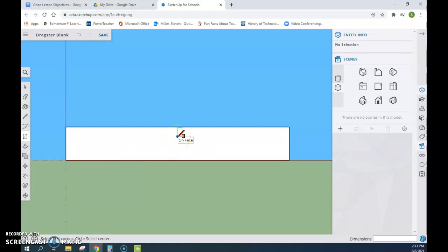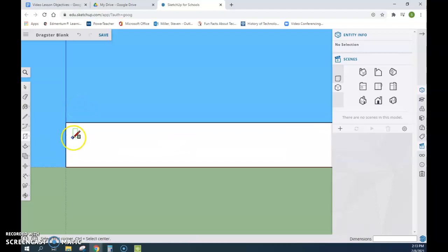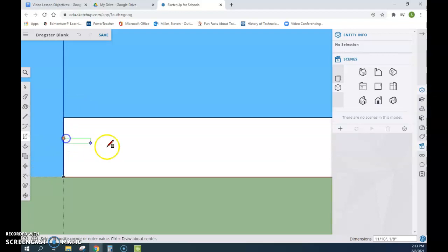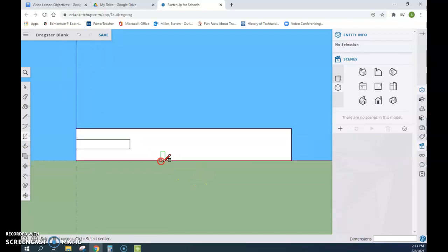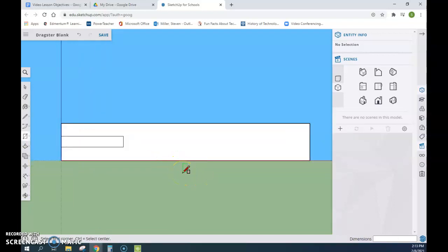All right. So now I'm going to go ahead and hit the space bar, and R for rectangle again, and I'm going to make a little hole back here for our engine compartment. So I'm going to go about that far. It doesn't have to be very far in. If you look down here, you'll see how far you're going this way. So I'm going to put it about 2.5 inches, just about like that. It doesn't have to be perfect, doesn't have to be exact. Right about there is good. Okay, so I'm going to hit space bar again, and I'm going to hit save.